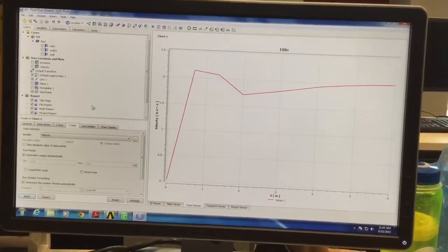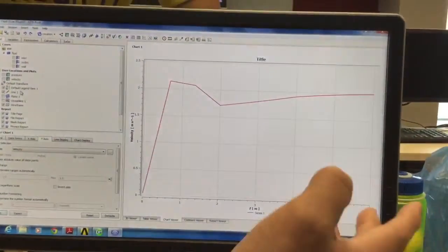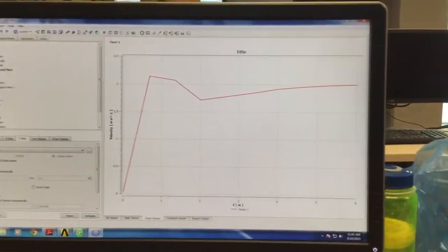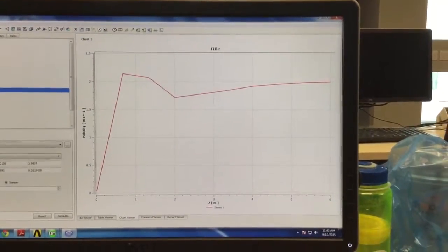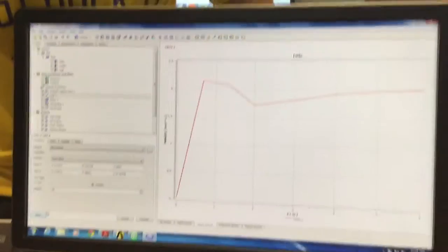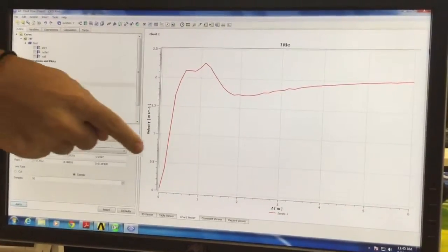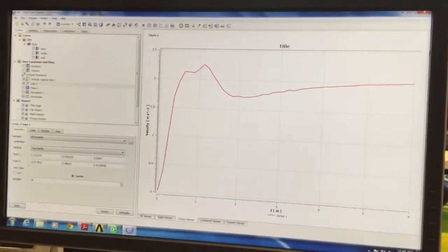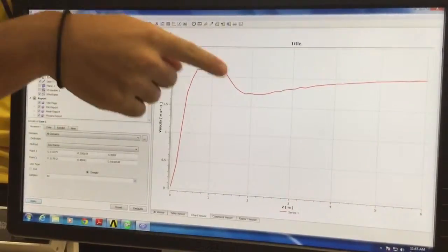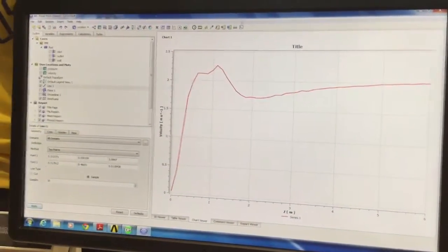If for example you want to see a smoother line, you can increase the points from 10 to maybe 50. Apply first, then you see what you get. You get a smoother line. It means increasing the number of points within the line, because it's more jagged, so it's more points.